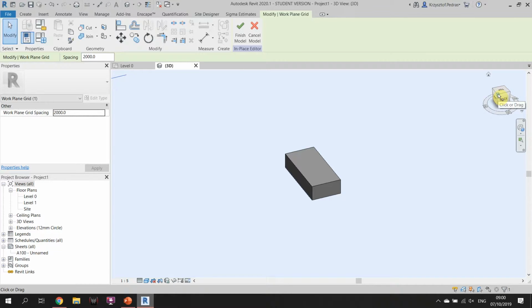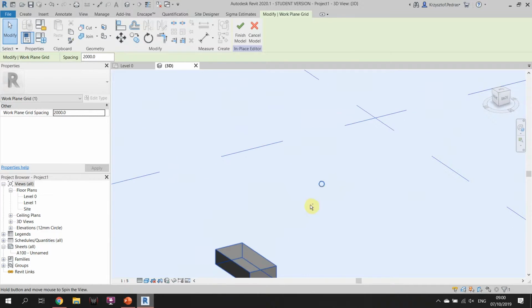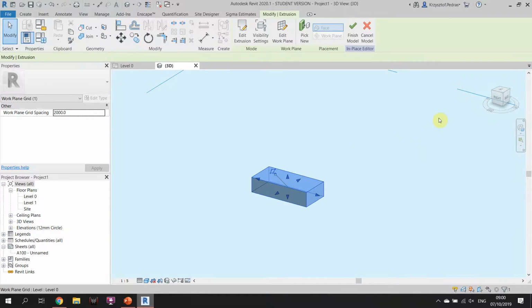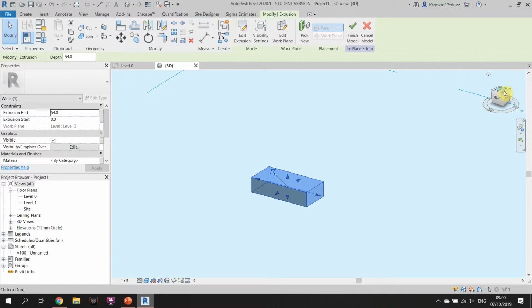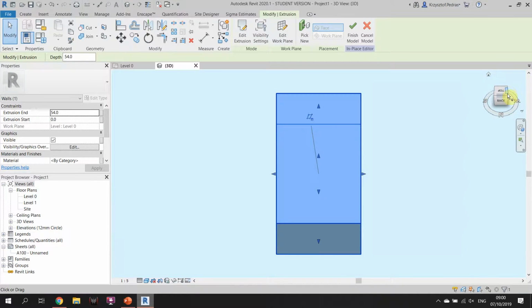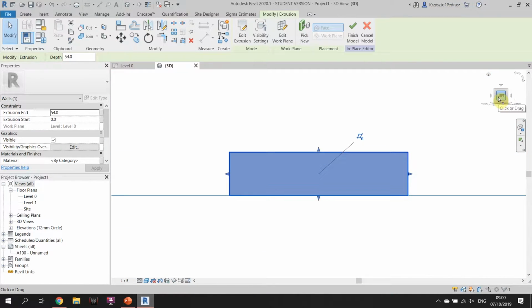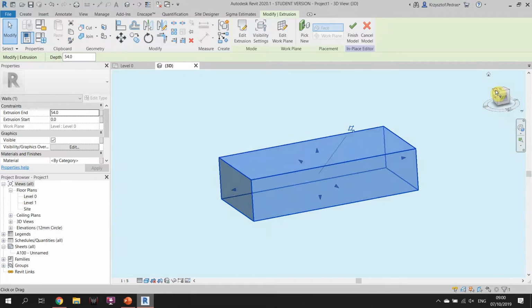Important fact, how to navigate also inside of the 3D because of the planes. If you click on the model or the object itself and orbit over it, it's gonna take this one as a center. And you can do the same using this cube. Whether you're gonna click on any of the sides of the cube, corners, to get flat image or 3D image.